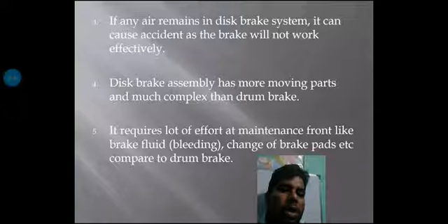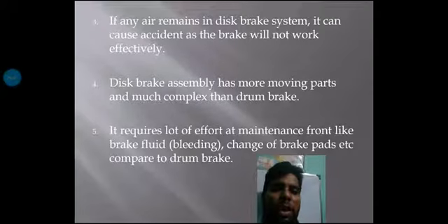So the total actuating force capital P will be the average intensity of pressure, indicated by small a, times the area of the pad, capital A. So total force applied on the pad is equal to the average intensity of pressure times the area of the pad.